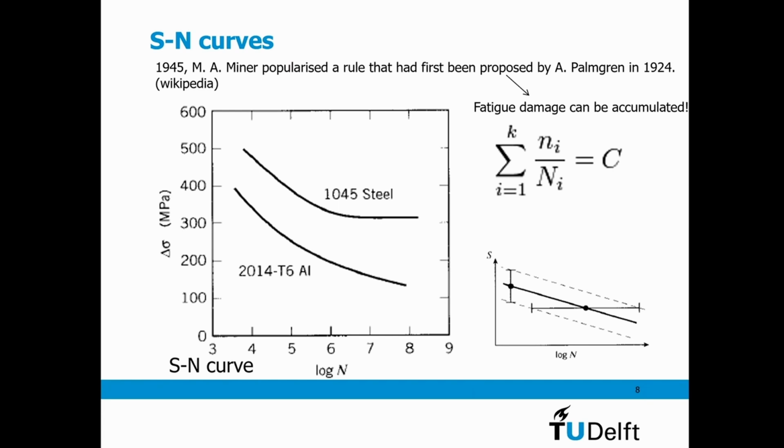where he made a curve where you have the number of load cycles, which is on the lower left, on a log scale. So 3 means 1,000, 10,000. So this is 1,000,000, and this is 10 million. 100 million. Number of load cycles, and you have 4 different types of steels and materials. You have these fatigue curves.